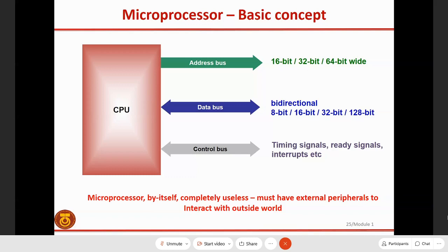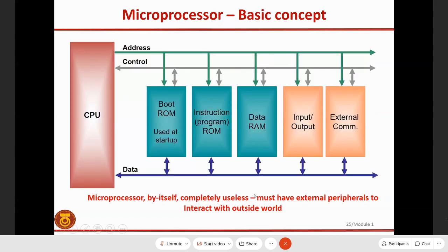So this is what the CPU tells the others, but using the control bus. It's not everything lumped on the address bus. Address bus does not send every instruction. The address bus is dedicated for addresses only, so that once the memory reads, it only reads from the address bus. But the control bus is dedicated to controlling the operation, whether to lock, now you send, now you read, now you write, something like that. Yeah? So that's how the control bus runs the operation.